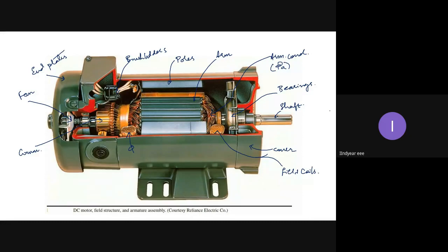Okay. So for that, what we can do is we can increase the length of the machine. If I keep the bearings a little bit away from the active armature area, then the reluctance between the armature and the bearings will increase, and probably the flux linkage may not happen, and the circulating currents can be minimized. But if I do that, the material required will increase, the machine becomes bigger, and more cost will be incurred. Okay, so that is a design problem.